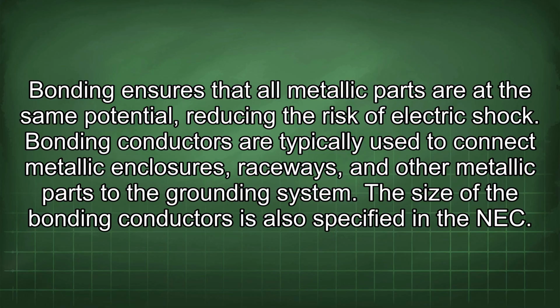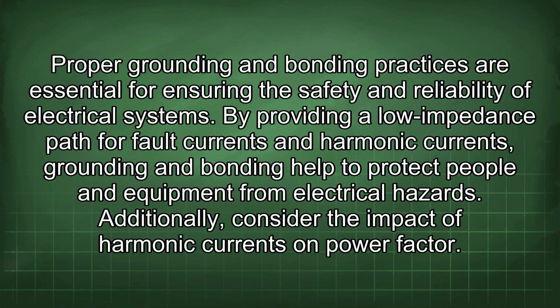Bonding conductors are typically used to connect metallic enclosures, raceways, and other metallic parts to the grounding system. The size of the bonding conductors is also specified in the NEC. Proper grounding and bonding practices are essential for ensuring the safety and reliability of electrical systems. By providing a low impedance path for fault currents and harmonic currents, grounding and bonding help to protect people and equipment from electrical hazards.